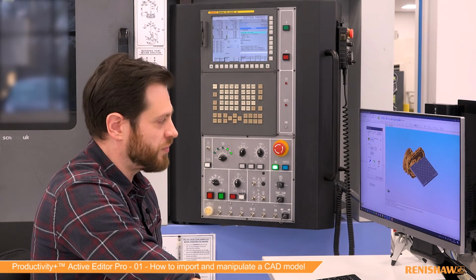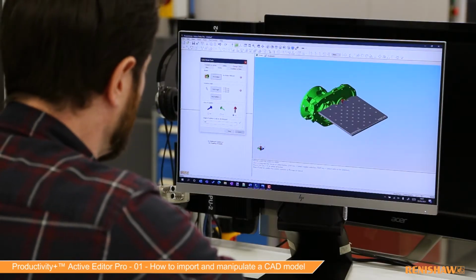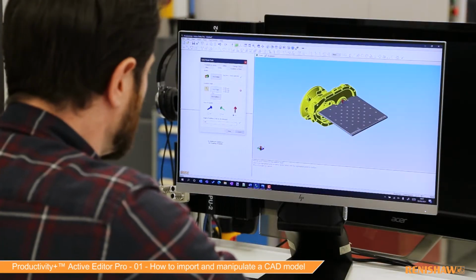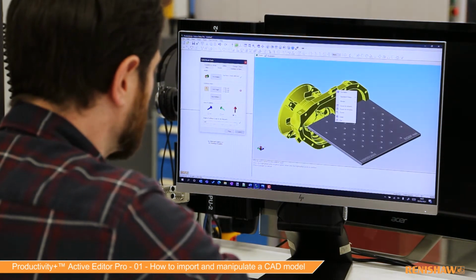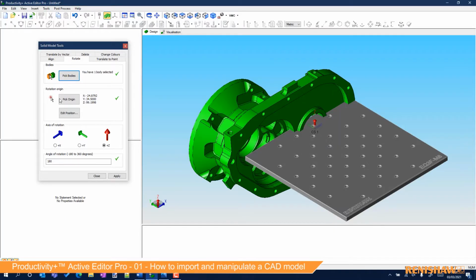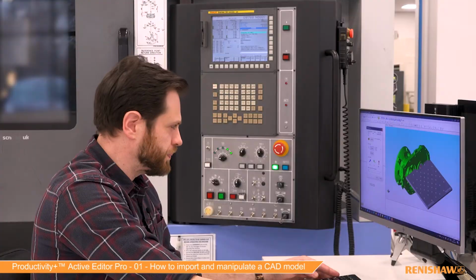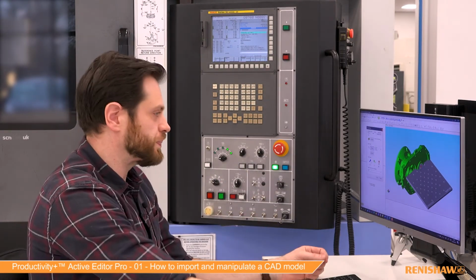now all the models that we've got here and all the functions, we first will need to select the model that we're going to move. So if I choose this pick bodies and select our parts, the next thing I need to do is choose an origin point. So this is where we're going to rotate the part around. So if I zoom in just using the mouse wheel, now as you move your mouse around the component, you will see various elements get selected. I'm just for now going to choose the midpoint of that line, just to show this example. So we're going to rotate around that point.